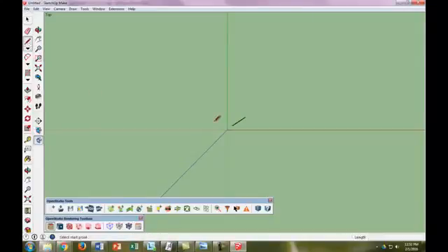With OpenStudio, what you really want to do is draw the 2D floor plan, and then you'll see that we just pop it out to the floors, or to the building that we're going to construct. So let's go ahead, and I'm just going to construct our first wall. The other big thing with SketchUp is you never want to click and hold. You want to just click and then leave your mouse free. So I'm not holding the mouse button right now. I just clicked once on the origin. And now I want to go up 25 feet.